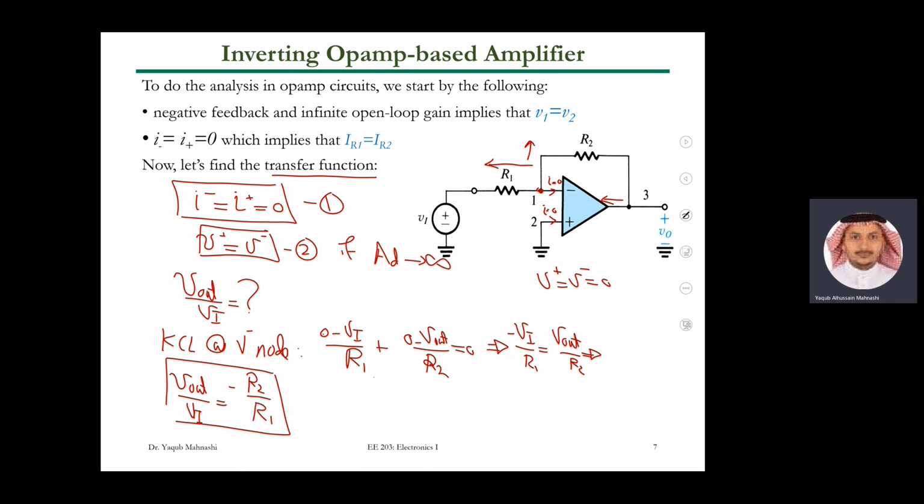This is very important, guys, and it ties things together. If you have an output voltage that exceeds your power supply, the op-amp will not give you that. It simply cannot. I don't have it to give you; where would I get the volts from? So keep this in mind.